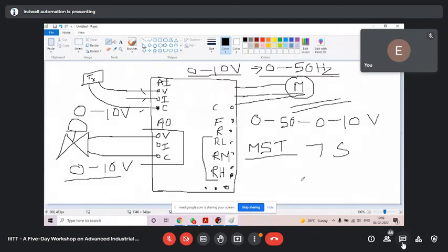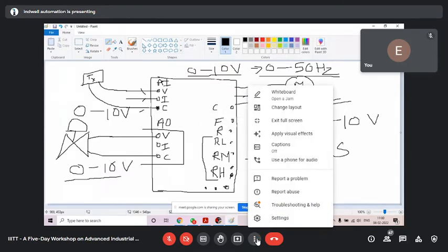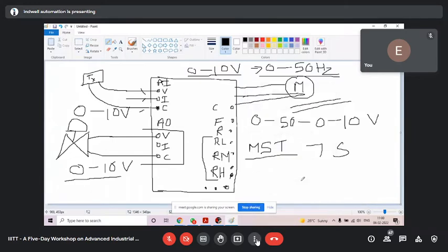So how will you increase that in that case? So there AC drive will be used. For those special purpose operations, special motors will be designed which can run on high frequency. Your AC drive can increase frequency also. It's not like it will decrease only below 50, but it can increase also above 50.